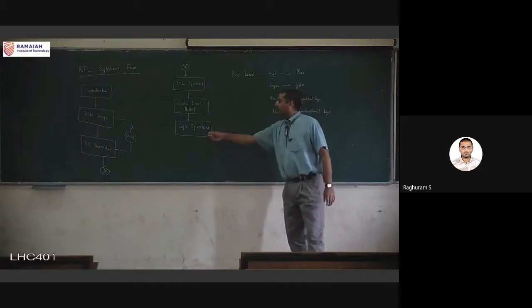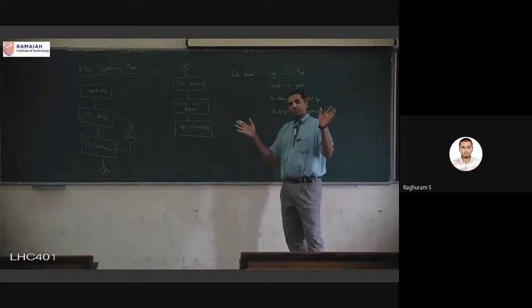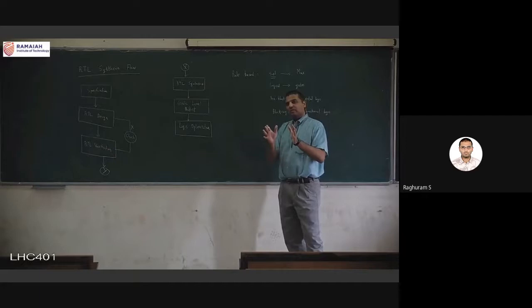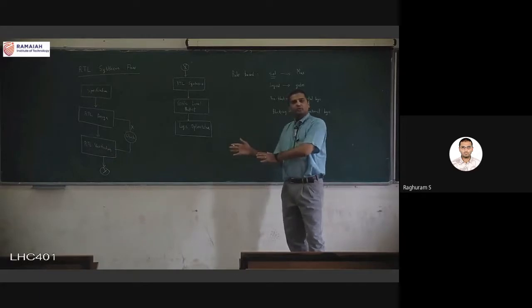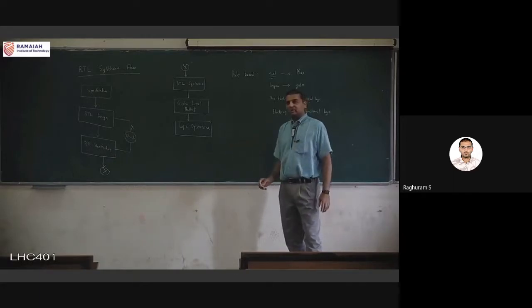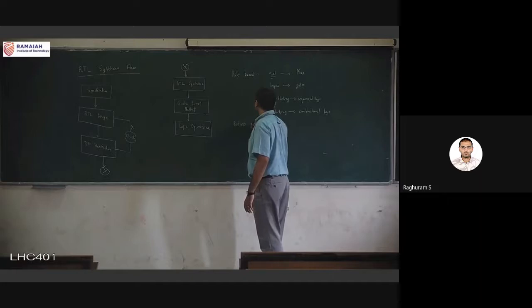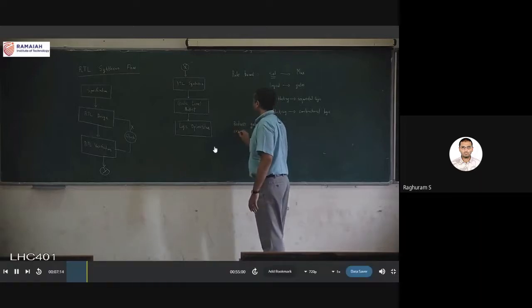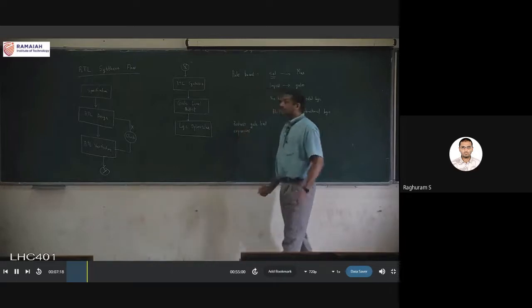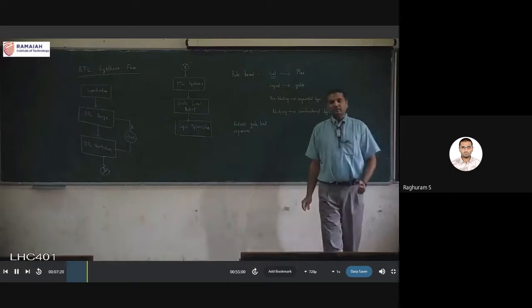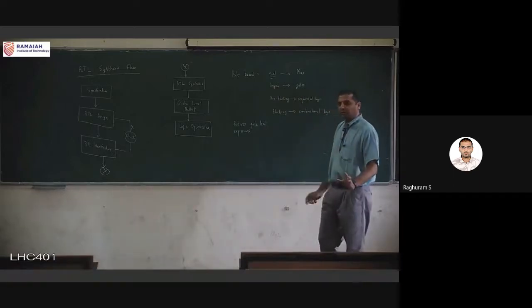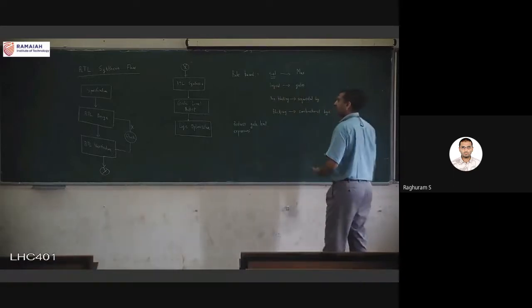But basically what happens here is the input is also a gate level description, a gate level netlist. The output is also a gate level netlist. But it reduces the gate level expressions. It doesn't transform the code. It's from gate level to gate level only.